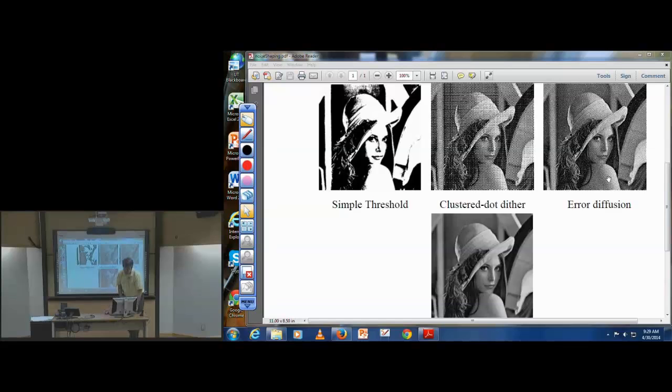This was invented in 1976, and the authors are Floyd and Steinberg on this paper. They sort of, by trial and error, found a really nice method to control where this quantization error goes. So if you go back to simple thresholding, if I just threshold with one value, then I'm generating quantization noise, or quantization error, whose frequencies spread out over all the frequencies and kind of just wash out high frequencies as well as low frequencies.